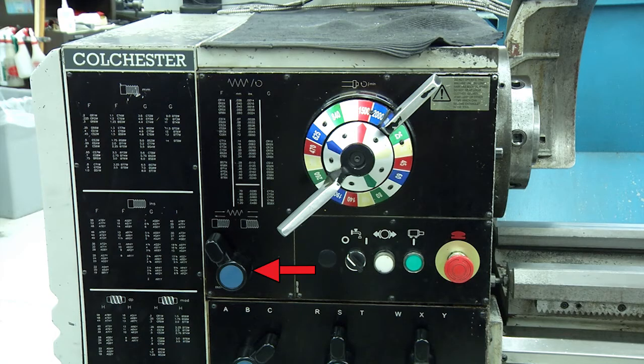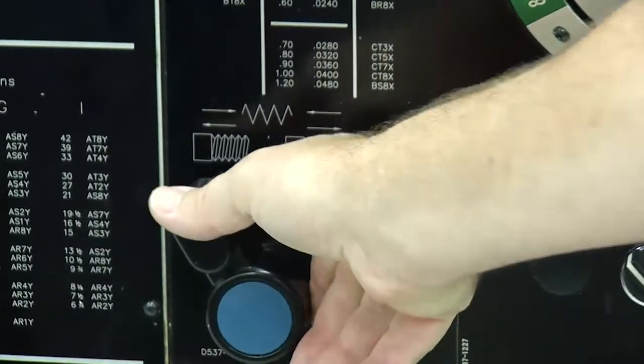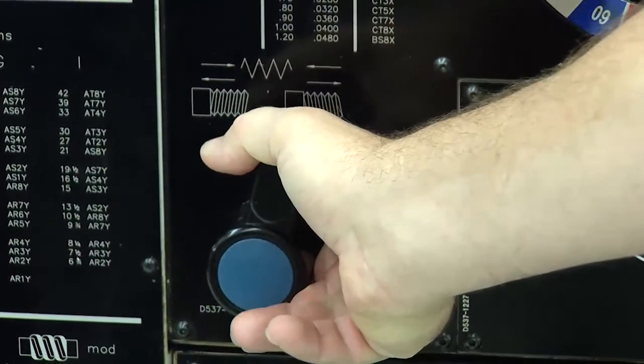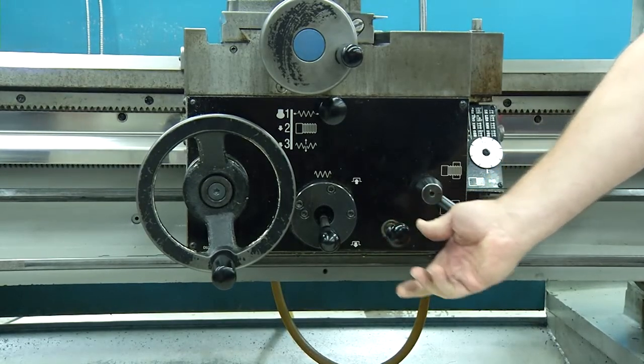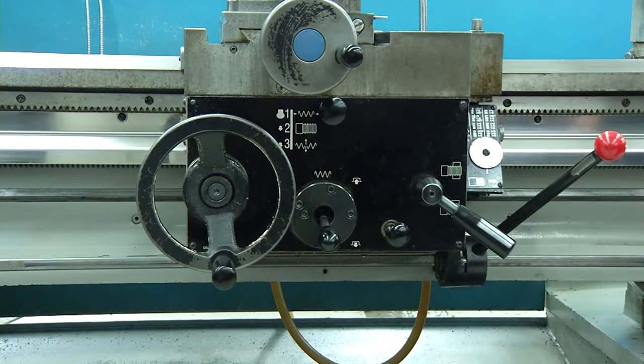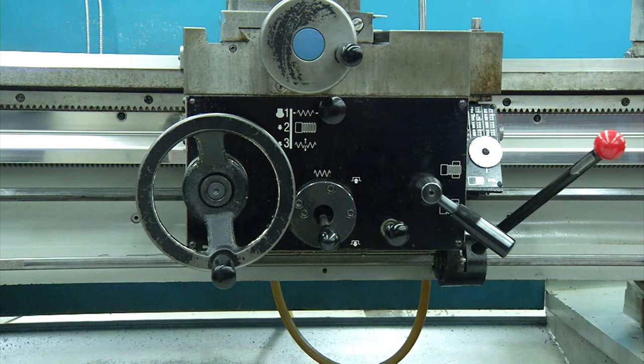The feed direction lever, or feed reverse lever, controls the direction of lead and feed screws. To change the direction of the automatic feed on the lathe, change the position of the feed direction lever. Pulling the saddle lubrication handle pressurizes the lubrication system and pumps oil to the longitudinal and cross slides.